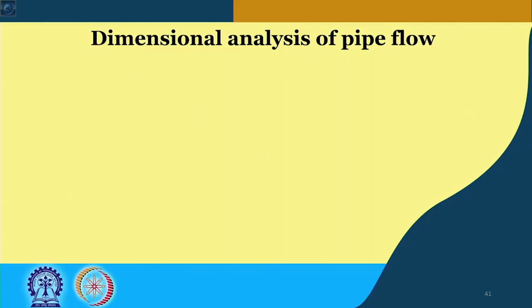Welcome back. So last time we solved a question using the laminar and the turbulent shear stresses. We calculated the laminar viscous sublayer thickness, then we calculated the centerline velocity using those equations of turbulent velocity profile, and then in the end we calculated the ratio of turbulent shear stress to laminar shear stress and found out that the ratio is more than 1000. It was almost 1217, indicating that in a turbulent flow the ratio of turbulent shear stress to laminar shear stress is very high. Okay, so in turbulent flow the dominating shear stress is due to the turbulence.